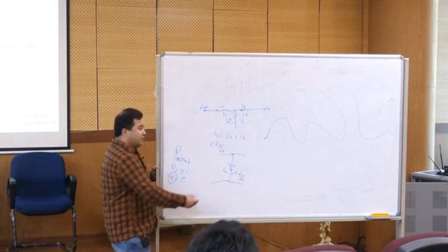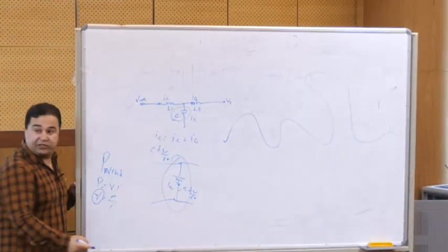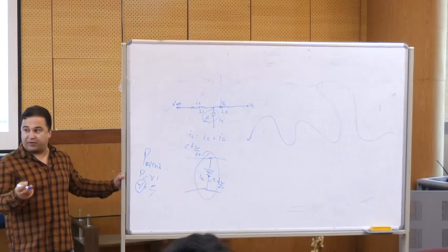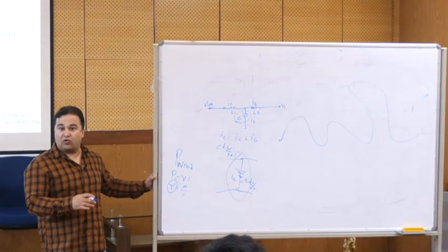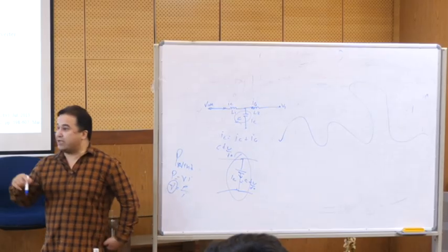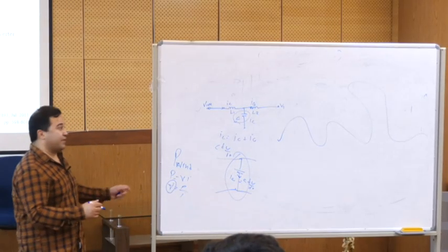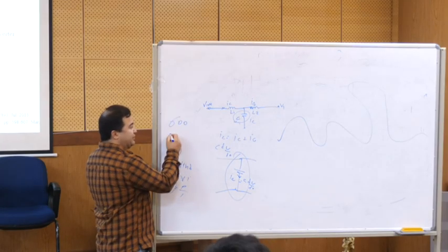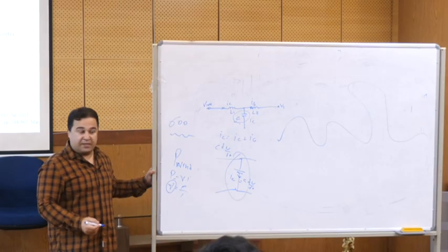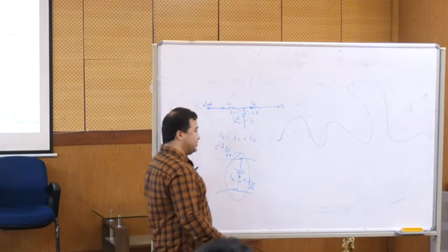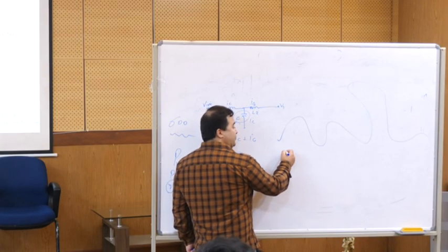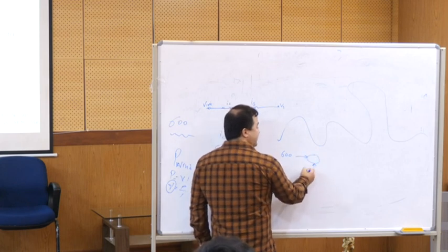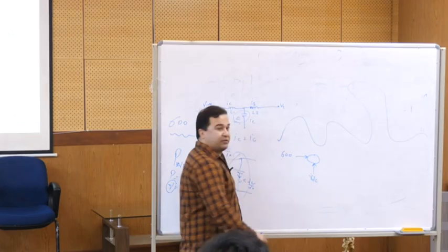For this reason, we need the regulation, a voltage regulator here, which can also be based on an extra DC-DC converter added on the DC side. Or, for example, the VDC we need is 600 volts, but we have some fluctuation. So we said the reference voltage is 600, but the voltage that we have, VDC, is not 600.